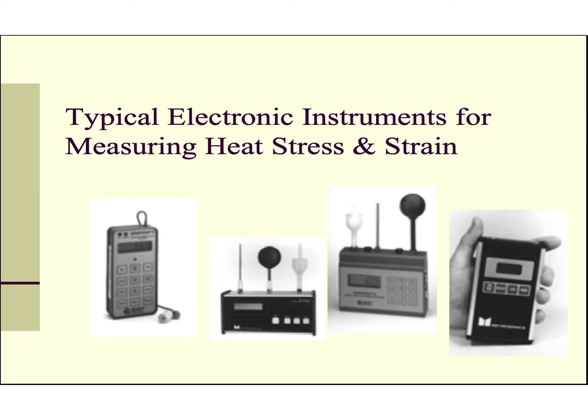It's possible to make up a simple group of instruments to measure WBGT, globe thermometer, wet bulb thermometer, and dry bulb thermometer, but very often these days they're done with electronic instruments. The two instruments pictured in the center are for measuring WBGT. The one on the second from the left, for example, is a dry bulb thermometer on the left, globe thermometer in the center, and a natural wet bulb thermometer on the right. The cup houses the wick, and there's a water supply there to keep it wet.